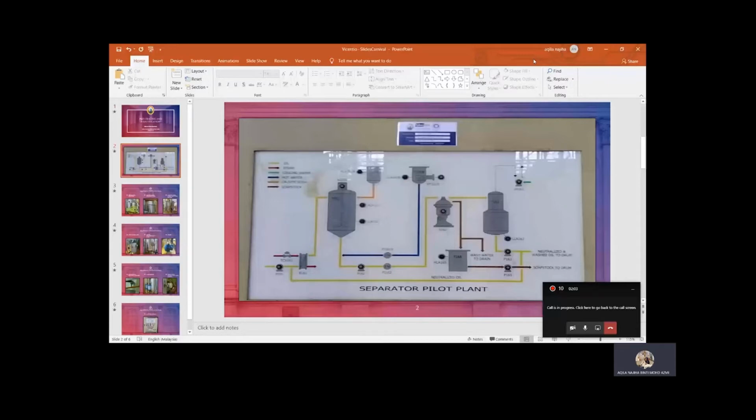The maximum operating condition of the pilot plant is 300 to 400 tons. The optimum operating condition is around 70 to 90 degrees Celsius. If the temperature is more than 100 Celsius, it can cause damage to the separator. The pilot plant is not used for experiments, and is only used for oil testing for oil producing companies like FGV Holdings Berhad, as the capacity of the pilot plant is too big for experiments, which may cause a higher cost.